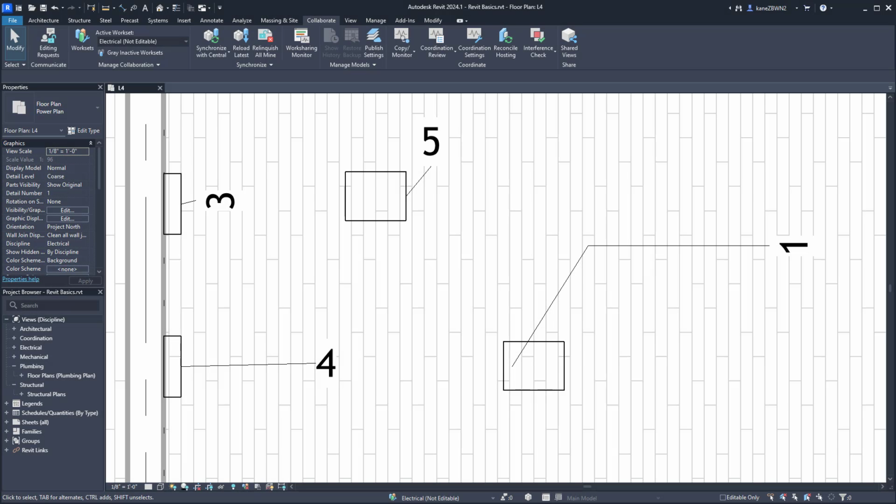Moving away from worksharing, next we're going to talk about phasing. Oftentimes, especially if you are working on an existing building, the project will have interim states for demolition, temporary MEP arrangements while new stuff gets built, and so on until you reach the final product. Revit lets you model each of those phases within a single project.